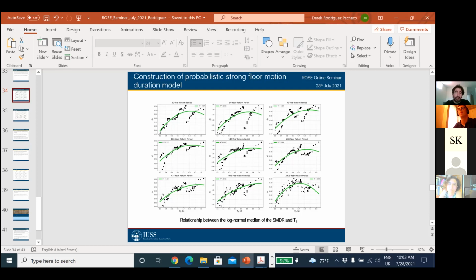With the exception of the contents, as you mentioned. Depending on the classification system you use, contents are sometimes not considered a non-structural element. Because the content is not anchored to the structure, it can move more or less freely during a seismic event, which alters the behavior a lot. So basically, I would say this was developed for buildings and for anchored non-structural elements.